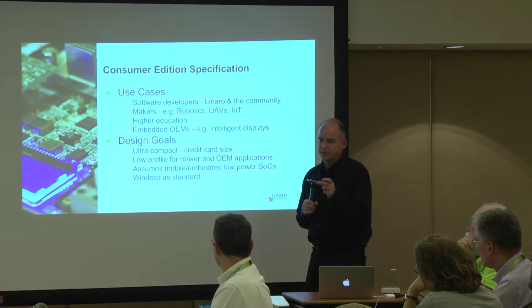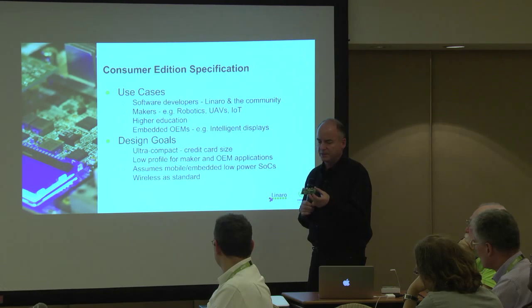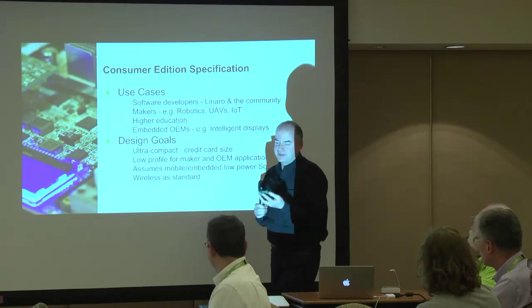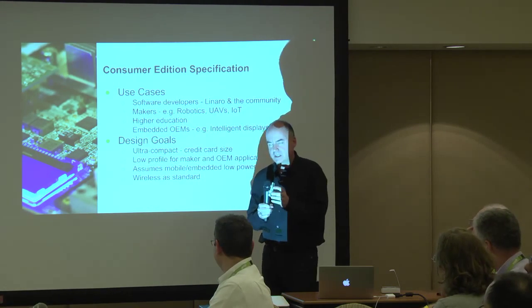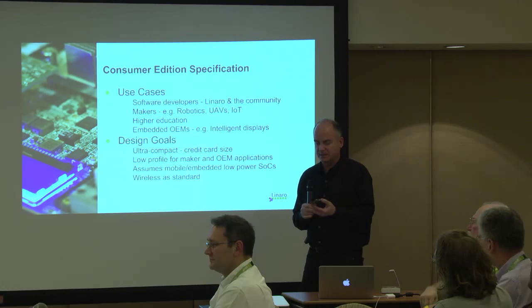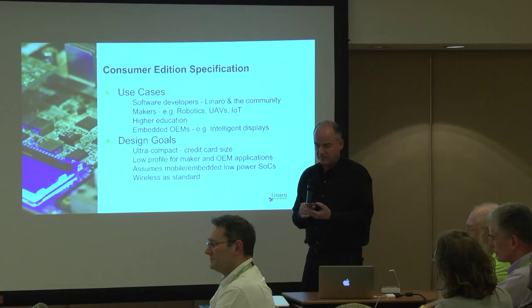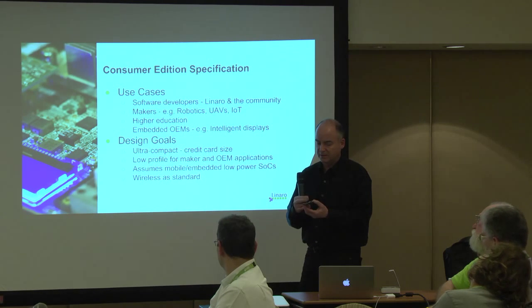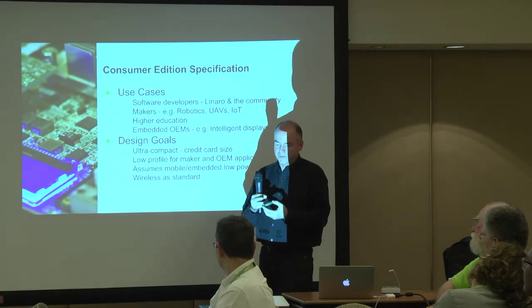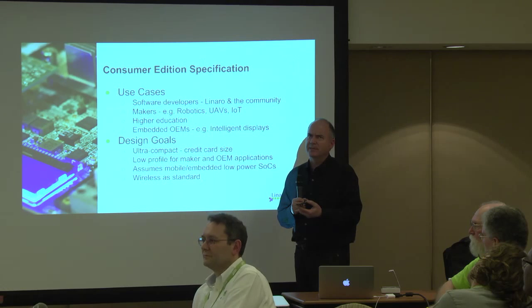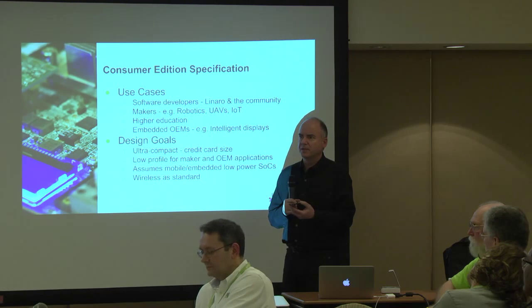what you end up with is a board that actually can be used in a lot of, whoops. That's called the drop test. That can be used in a lot of different very low profile and small format applications like robotics, UAVs, and so on. The trade-off is that you have certain constraints in terms of obviously vertically mounted components and also thermally. The 4-pin header that you first saw on, we made an initial prototype batch, I think, of 50 boards.